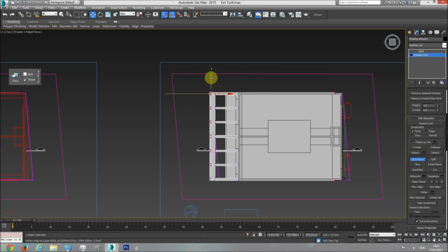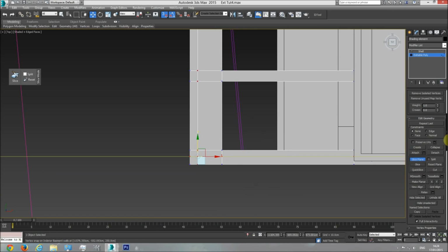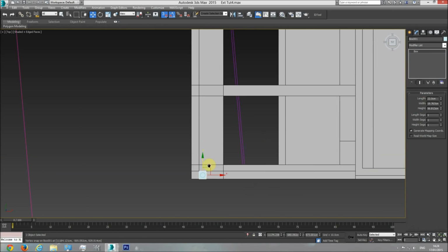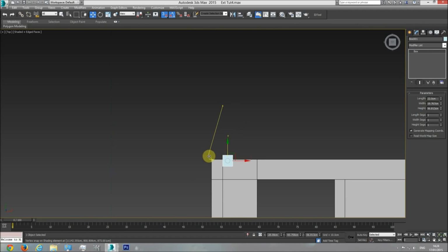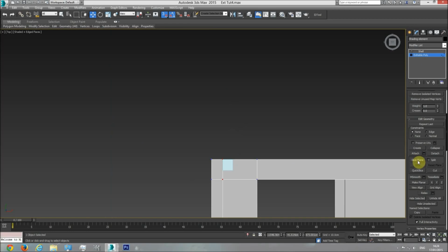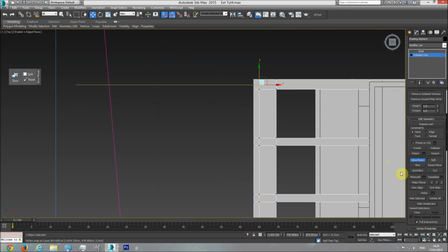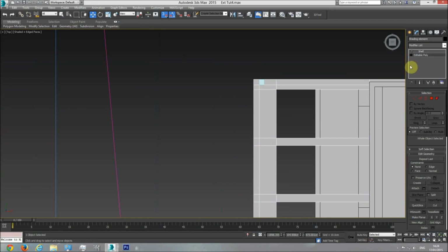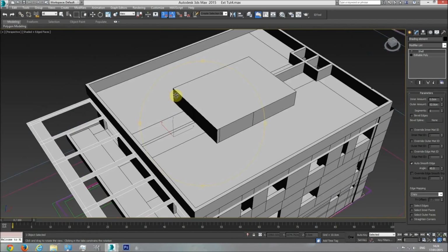And take it down to the line where the helper box, slice plane. Let's take this helper box up here. And again, vertices, slice plane, take it up here, slice. It's great. Let's delete the box and see what we need to do here.